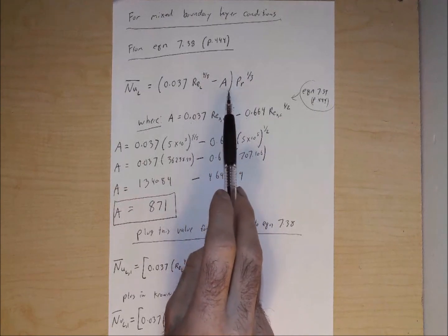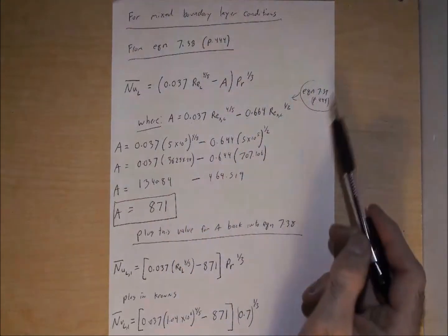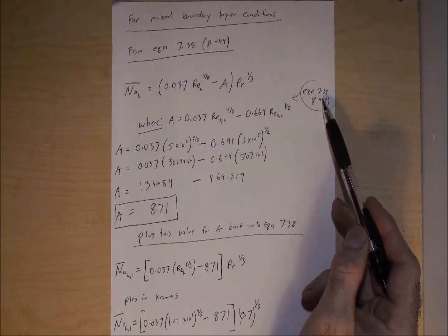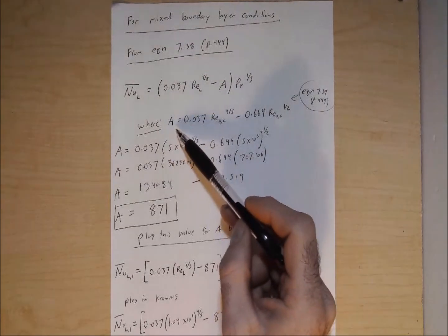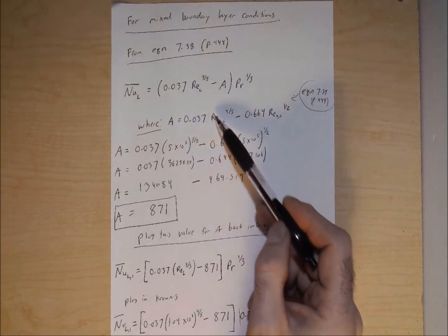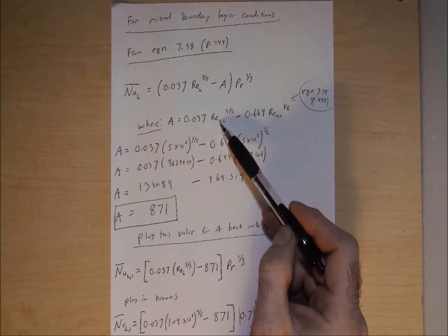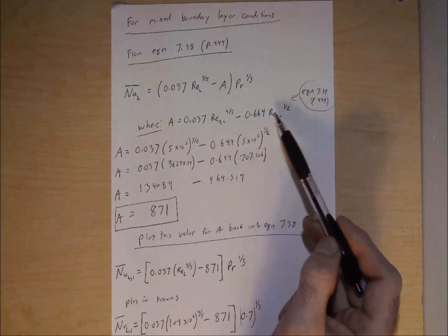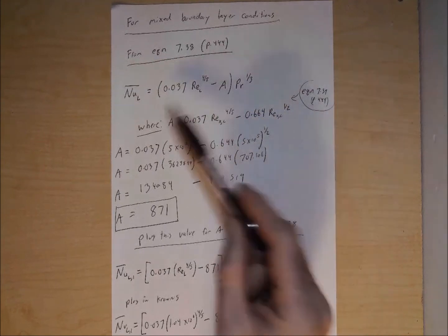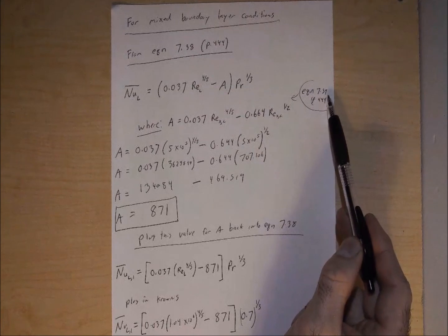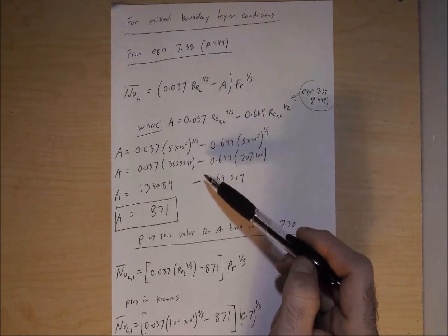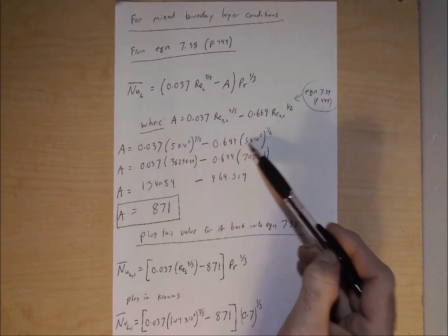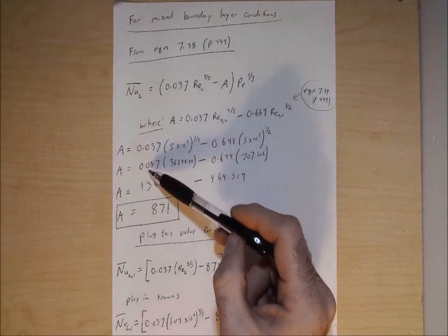Now we need to figure out a relationship for A. Where this comes from is equation 7.39, on page 444 of our textbook there. If we take a look at that, we get this relationship for A, where A is equal to 0.037 times Reynolds number Re sub xc to the 4/5 minus 0.644 Re sub xc to the 1/2. From this relationship in equation 7.39, we can then plug in our known values. We have a known value for our Reynolds number that's given to us in the problem statement. We can plug in for both of those. So A, when we plug that in, becomes